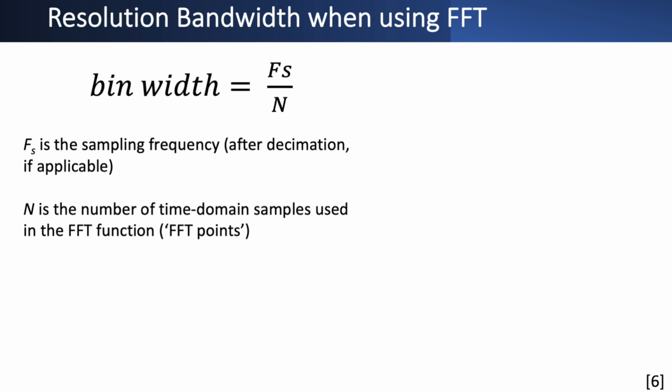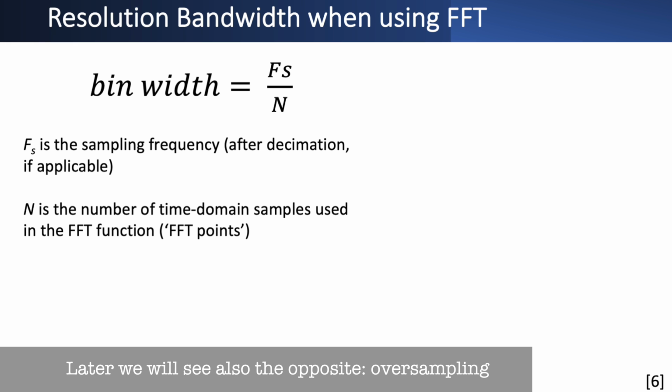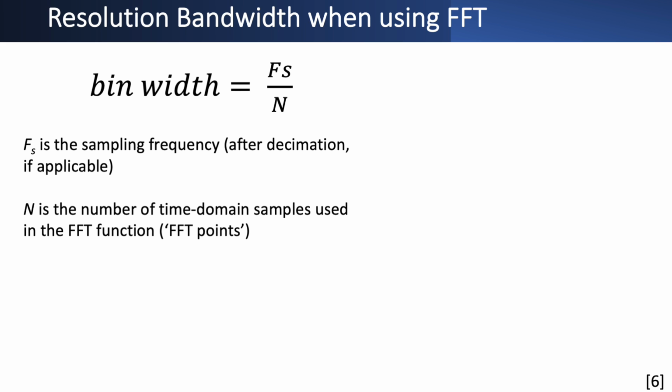That might not be the full sample frequency the device is running on, because that might have too many observations to be processed by FFT, and then decimation might take place. They might make a selection of those. So we need to know the sample frequency going into the FFT to know something about the bin width.